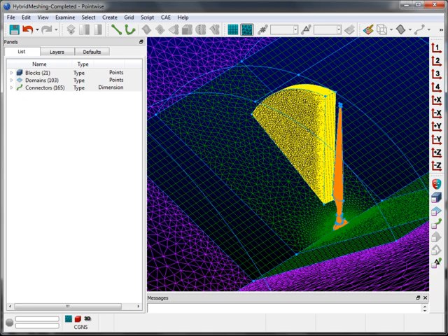this video. So horizontal axis wind turbines, like the CX100, generate power through lift. Therefore, efficient designs must have low drag. Now, aerodynamic drag is really created in two regions of the flow: the boundary layer region, like around the blade and the hub, as well as the wake. So being able to resolve these two regions accurately is key.